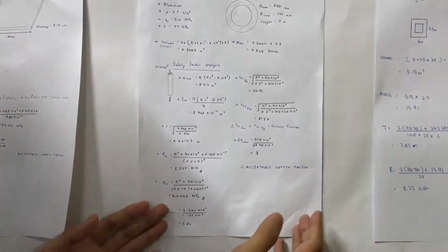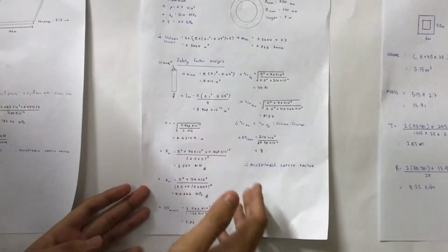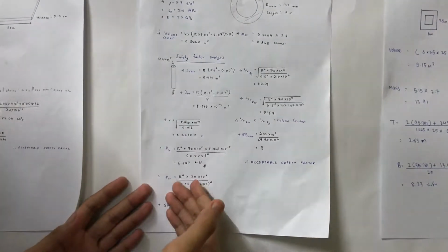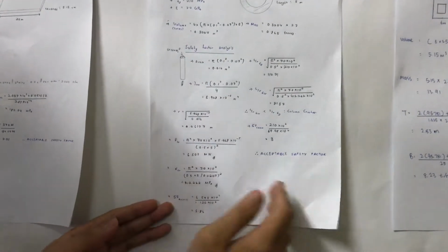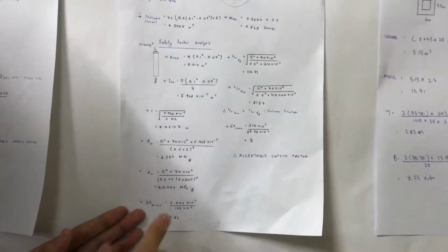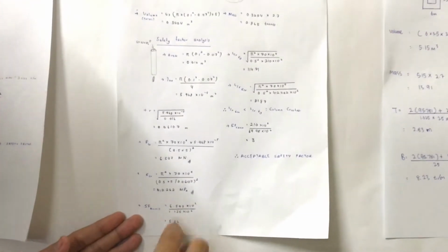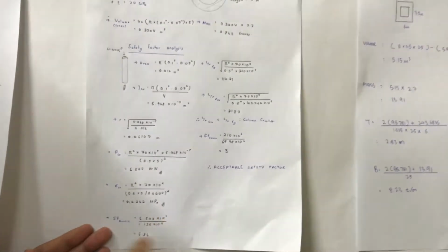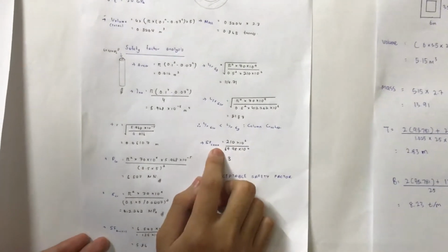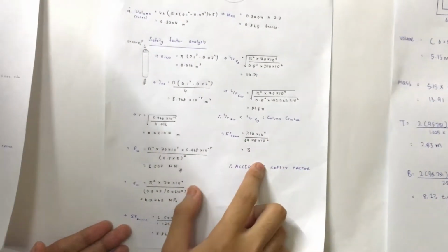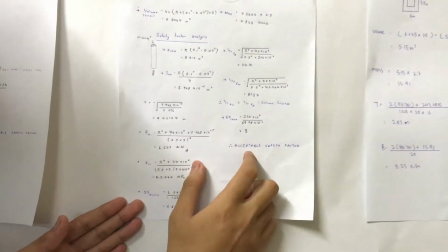And then after we calculate the R, the PCR, the CCR, we get the safety factor of the buckle, and the safety factor of the buckle is 5.86, that is considered safe. And then we calculate the safety factor of the crush, and we get above 3, and it is considered acceptable, and the column is in a safe position.